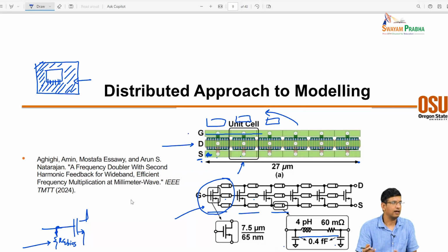regardless, right? But what is the key metric that is most sensitive to all this is width per finger. That metric, if you make it very large, you immediately see an fmax impact. Because there the gate resistance is in poly, so it's not in metal. So it immediately adds to your RG and degrades your noise figure and degrades your fmax.